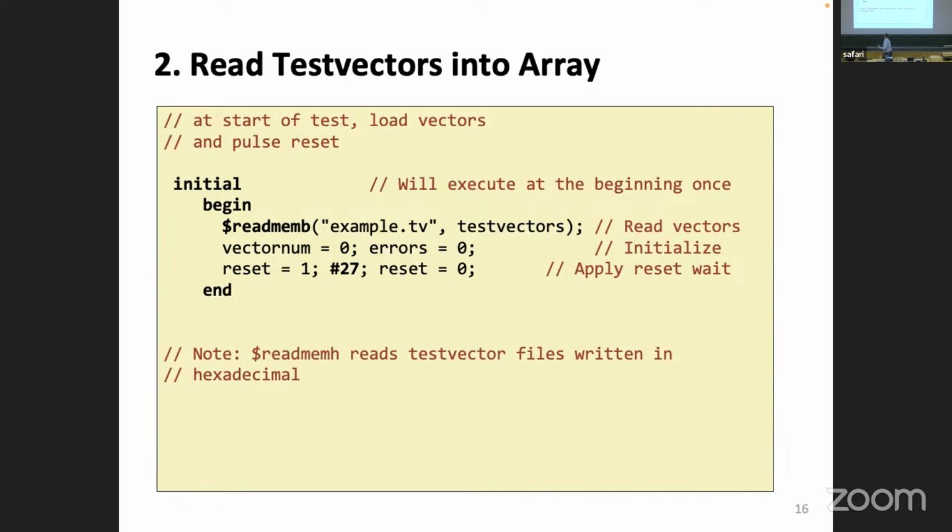Look, the story is here. So this is 0, this is 10, this is 20, this is 30. You don't want inputs to change at the same time as the clock. You want a separation between them. So waiting for the reset for 10 or 20 or 30 would not be a good idea.